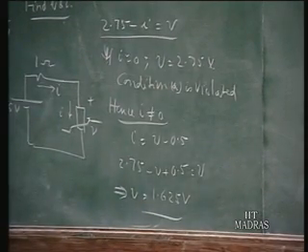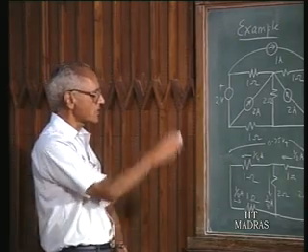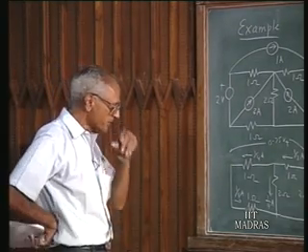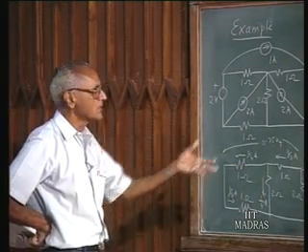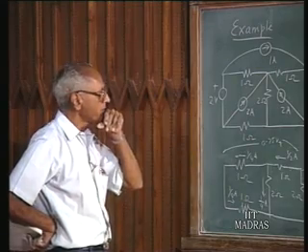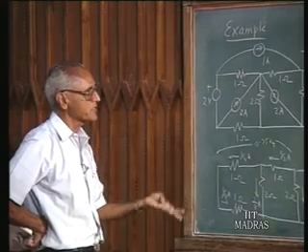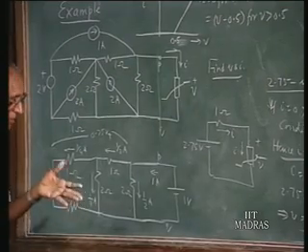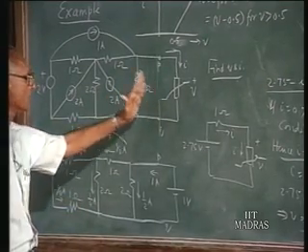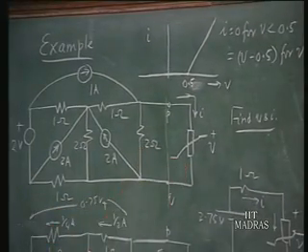So this example gives you a nice illustration of various principles that are involved, various network theorems. We used, for example, Thevenin's network theorem, and then we have used the series parallel reduction technique for calculating the currents here. We used the principle of superposition because we found out the effect of various sources on the open circuit voltage. We used reciprocity theorem. So we have used reciprocity theorem, Thevenin's theorem, superposition theorem to calculate this answer. And we also have observed that Thevenin's theorem can be applied when the load network is nonlinear. This is an illustration of that particular property.